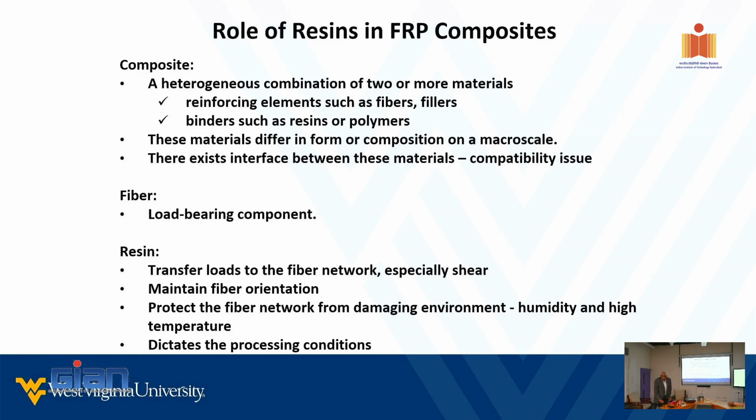So in my 100% thing I told you, I kind of broadly categorized roughly 60% fiber, 40% resin. In that 40% or 45%, however hard you try, you cannot make the void content zero. Perhaps you can reduce the void content below 1%. The aerospace guys would like to reduce it below 0.1%. So that is where the Six Sigma comes into the picture, you see.